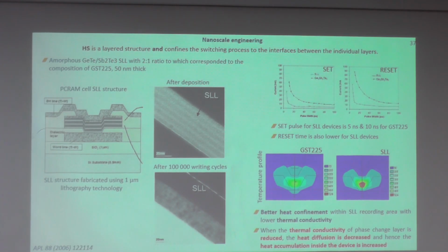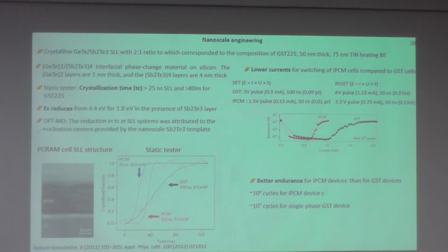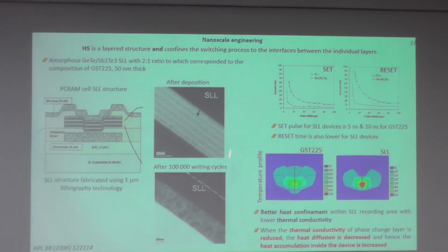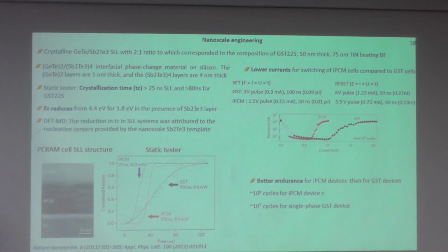These superlattices are based on amorphous crystalline layers, and if you use crystalline superlattices like textured or epitaxial thin films, then they can also get better performance in the sense of endurance and low currents.